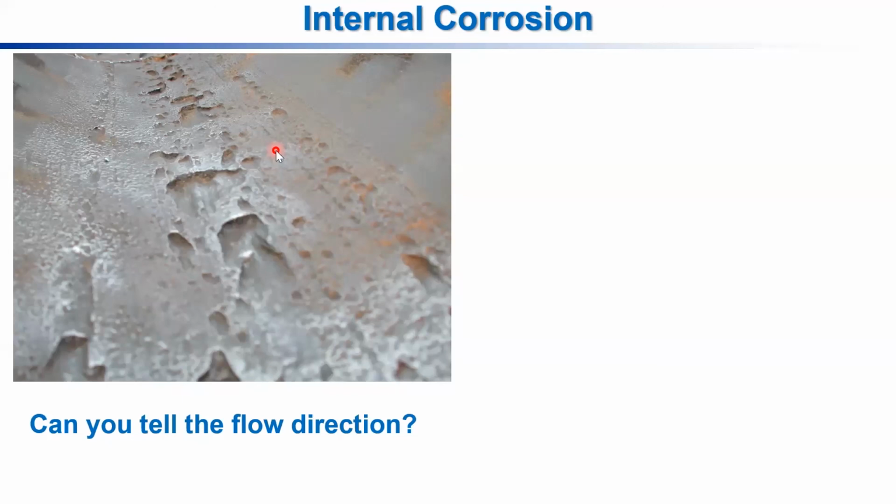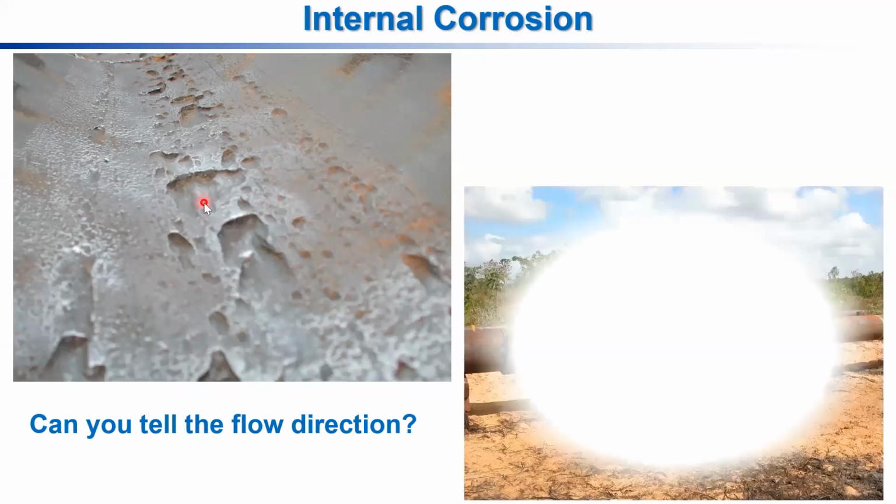In this case, of course, ideally it is to locate it at the 6 o'clock position, or from the 12 o'clock position running down a string all the way down to the 6 o'clock position. But the monitoring needs to be located in this region, the region that I'm showing right now on the screen. Otherwise, I'm going to be saying, well, I have low corrosion rates, and that is not true. So why do we need to know that? Because this is what we want to prevent.